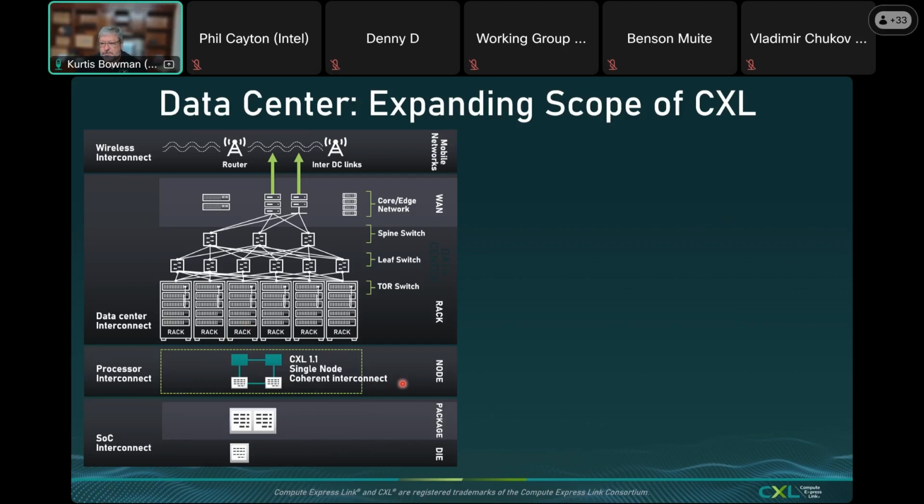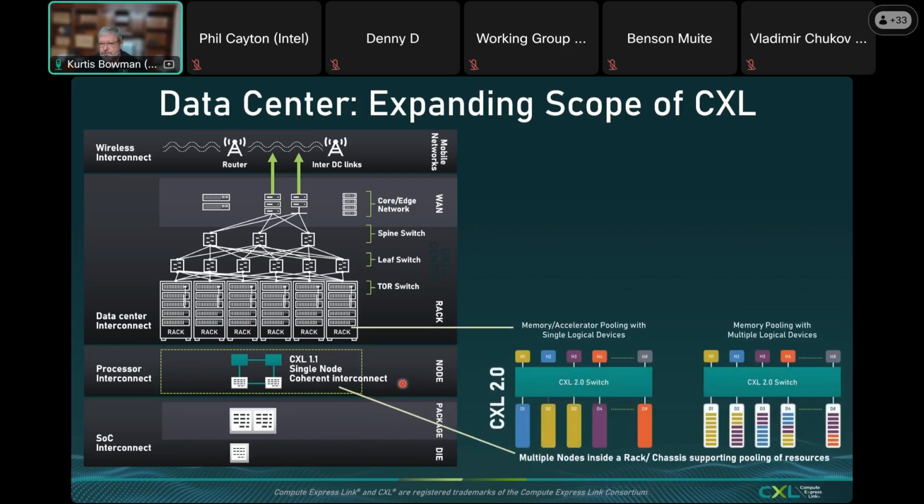Then as we moved along to 2.0, we started putting it together as a kind of PCI environment with a switch, but it still used all of the memory semantics, so the CPU can use its standard reads and writes, puts and gets across a very low latency, high bandwidth bus. And this is what's generally in the marketplace today, the 2.0 type devices.